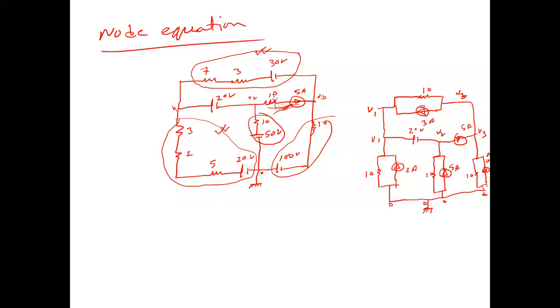Okay, and the third portion is our source conversion. Previously, when any current source was in parallel, we used the source conversion formula, current source to voltage source. But in this loop equation, for any voltage source with series resistance, we use source conversion, then it converts to a current source, and this resistance is in parallel. Okay, clear?